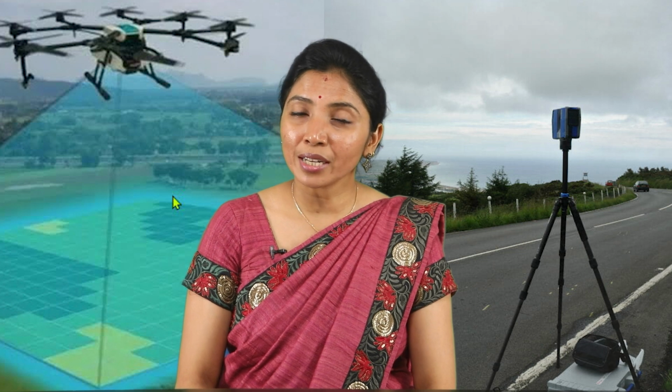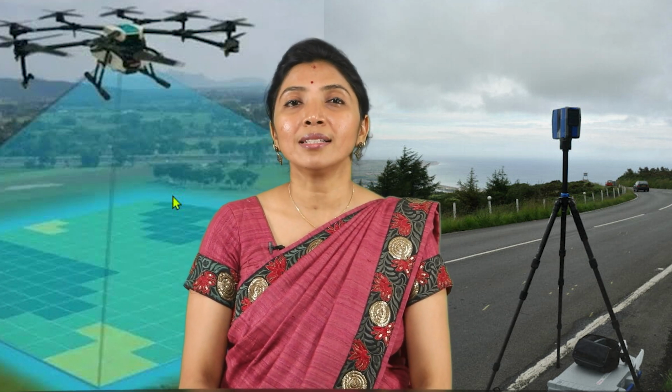The key concepts include calculating the relief displacement using the formula small d is equal to small r small h by capital H, and determining the object height and flying height from the photographs. We also discussed photographic overlaps to ensure complete area coverage and how to calculate the number of required photographs and the time intervals between the exposures with very good number of examples.